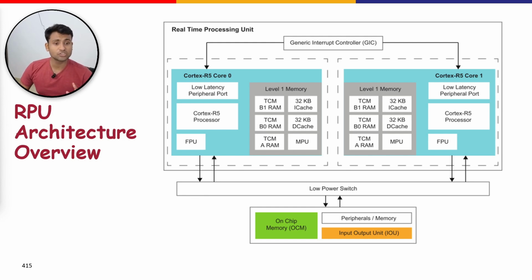The memory protection unit manages access requests to level 1 memory and external memory, permitting customization and partitioning of memory into regions, which is for protected mode of operation. The regions may then be assigned individual properties, and it is also possible to disable the MPU entirely, which will remove memory access management and set areas of memory to their default properties.